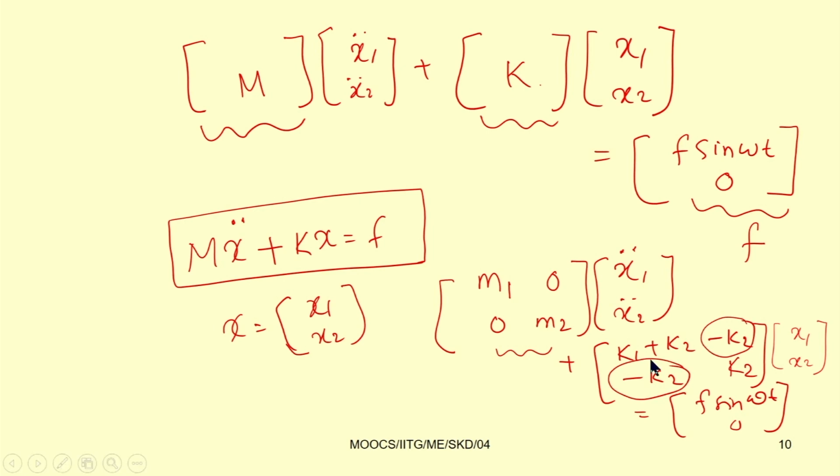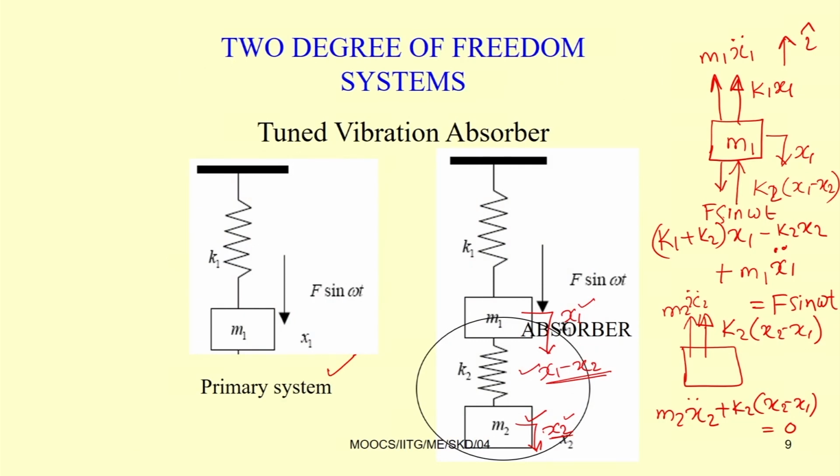Now we can introduce nonlinearity in the system. For example, let us put this spring to be nonlinear. So, we can put k 1 with nonlinearity alpha. In this case we have another force, that is alpha x 1 cube, so this equation becomes nonlinear. Similarly, we can introduce a nonlinear force between this and this. In addition to k 2 we can have another nonlinear term, and we can write down this equation of motion.